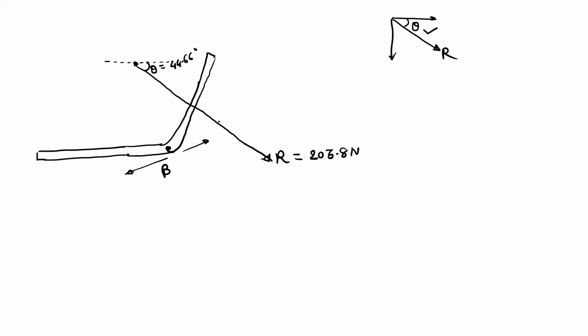So when we locate the resultant, just draw a line parallel to this resultant only. Somewhere draw one reference axis, show this resultant, and then draw this figure. And now we have to locate the resultant. That means we have to find the distance of this resultant along this line, or along this line. So this line is AB and this line is BC.